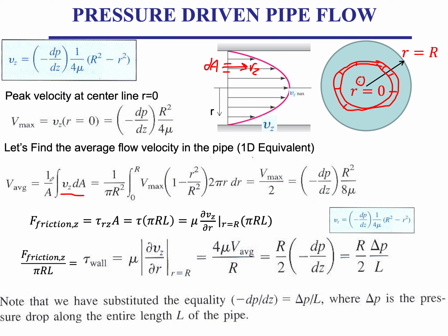so this is your volumetric flow rate, and you plug in for Vz this expression, times 1 minus r squared over R squared, times the area that we're talking about, which is 2 pi r, because the length of this rectangular strip is the circumference, 2 pi r, small r, and the width of this rectangular strip, because once you open it up it's going to be a rectangle, is dr. So 2 pi r dr, that's your area.